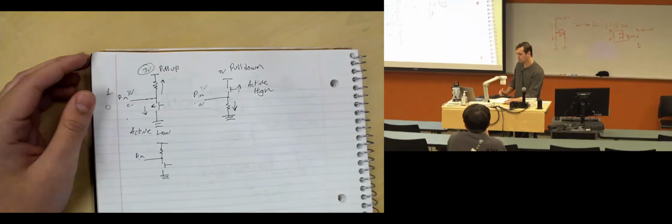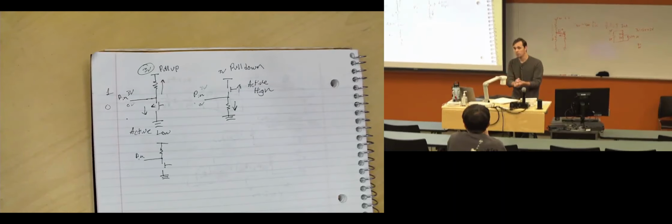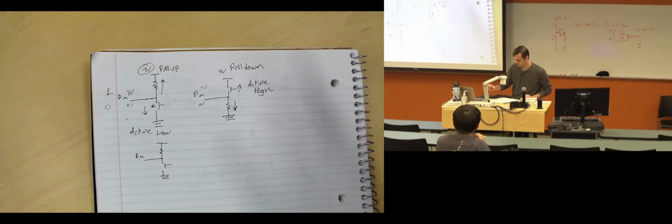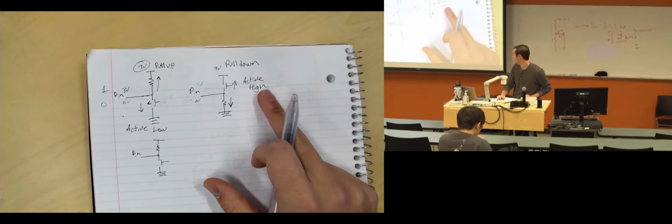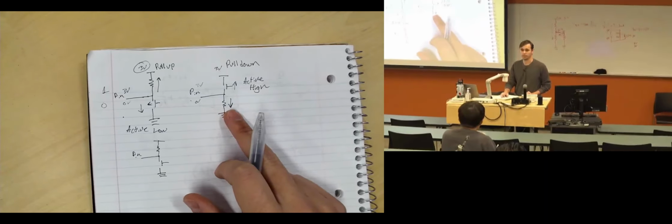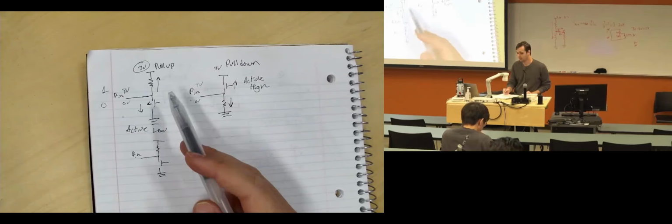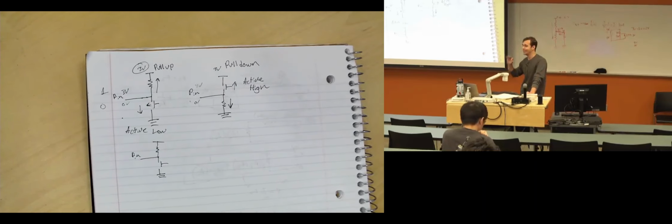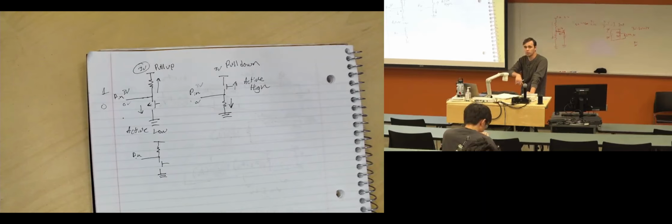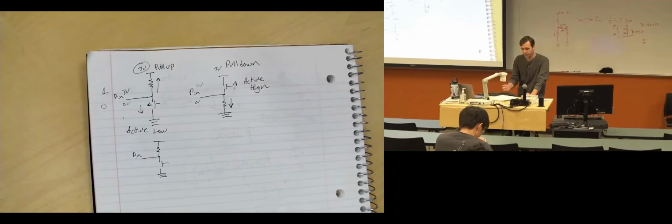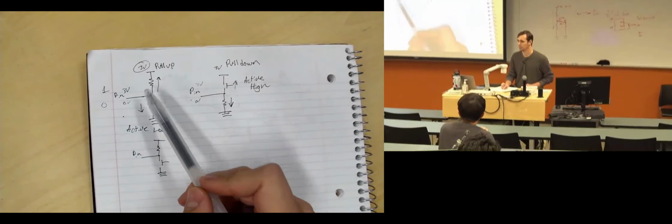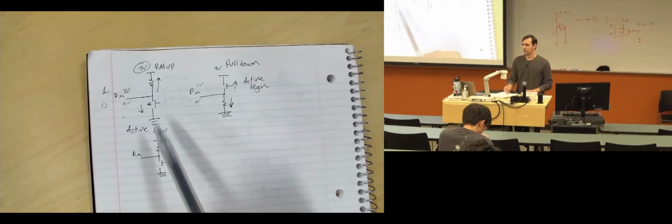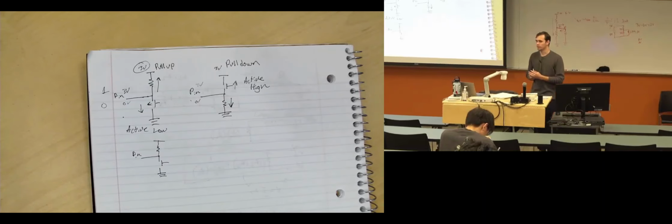So in lab 1 and lab 2, when you were using the STM board, and you were clicking the blue button and turning on the blue LED, that was active high, right? So that means the circuit was using a pull-down resistor, okay? And then if you've done lab 3 and you've worked with the FPGA, you know that the LEDs turn on when you write a 0, or the buttons give you a 0 when they're pressed. So that would mean it has a pull-up resistor. Does this make sense? Do we feel comfortable with pull-up, pull-down?